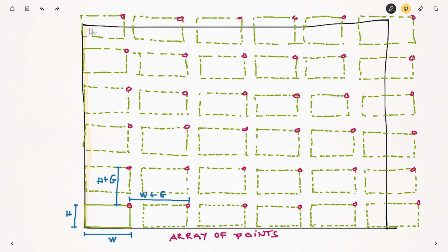Let's return to the sketch. Now we want to make sure that we will create only the number of solar panels that can fit on a given field. We will check each generated vertex inside of our field. If it is inside, we generate a solar panel. If the vertex is outside of the field, we will not generate panels.